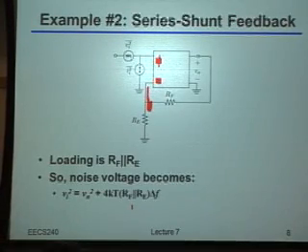What's bad about that? Why is that sort of really annoying? Yeah, there's going to be a lot of current flowing through them, right? And if you just think of this as a simple MOS-based amplifier, that also means you're going to be loading the output of that amplifier very heavily, meaning it's going to be driving a lower output resistance than you may have wanted it to be. Okay? So again, that's bad news.